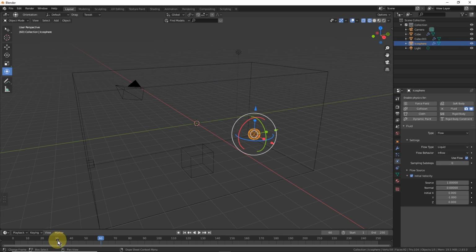And now we're gonna make a setting that it stops flowing. Now, this right here says that it's flowing. So all we need to do is set a keyframe at 20. Let's make it 25. We set a keyframe, pressing I or pressing that small keyframe thing here. We'll do that, and then we'll go one frame further. We uncheck that box and set the next keyframe. Now we got two keyframes here. One is with this flow checked, and the other one with it not.